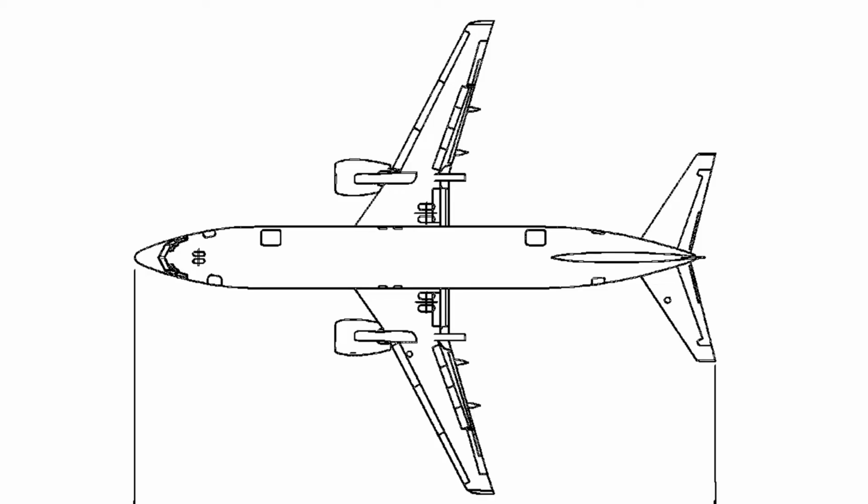You can see this effect a lot in the difference between civilian and military aircraft. Civilian aircraft need to have very efficient wings. So if you look at a 737, you'll see that it has very long wings that are kind of short and have a high aspect ratio. The downside of a high aspect ratio, though, is that the higher it is, the less maneuverability you have. If you have an airplane with really long wings, you can't exactly do extremely sharp turns and loop-de-loops and all of the stuff that military fighter jets like to do.